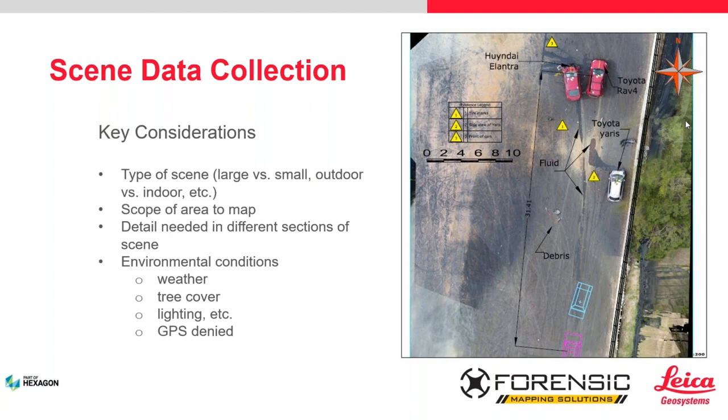And obviously the drone, and we'll get to it shortly, is going to give you a faster processing time. But some of the scanners like the LEICA RTC 360, it'll scan in 1 minute and 51 seconds your points and photographs. So the time that it takes to scan has gotten much better as well. But it's like anything else, you've got to pick the correct tool for the job.